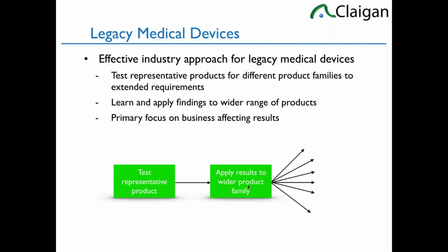We've already done ROHS. It's one of the ones that's a per material level. We'll test an individual representative. So we can't do everything. We'd like to, but we can't do everything. Do one representative of each product. Take the findings from it, particularly the declarations. A lot of the new regulations are declaration-based as opposed to stop ship. Create the declarations for them. If we have a non-compliance, deal with that non-compliance and then move forward. And handle new designs differently.